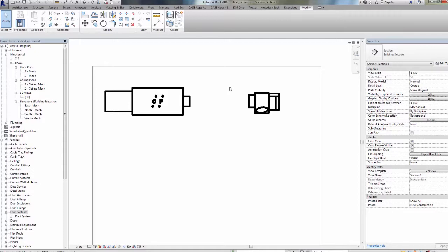Manufacturers have developed their BIM families in different ways, so unless there exists an agreement between all modelers, dimensions will be different. Nevertheless, because they have to coincide, in this case we are modifying the plenum, though the indoor unit could be adapted as well.